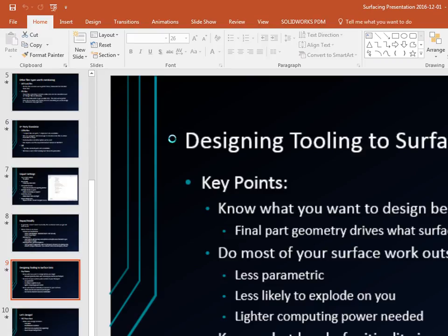So even stuff that knit will not do, even if you make your range up to like 5 inches or whatever, there's things that SOLIDWORKS cannot knit, but IGES will somehow do it where knit can't. So I don't know. Trim them and stuff like that. What does it trim? Trim them nice, because I know when you extend surfaces, sometimes you get them. Oh yeah. Glossing and stuff like that. Yep. It sometimes goes ugly on you. So yeah, I typically tend not to use that as a first resort, but it's a good last resort.